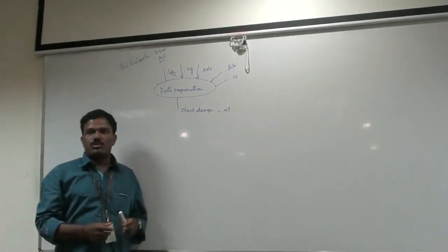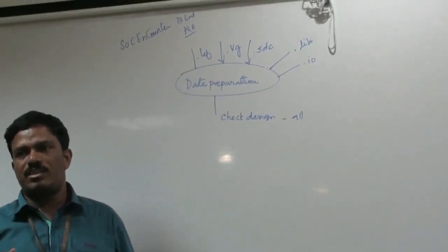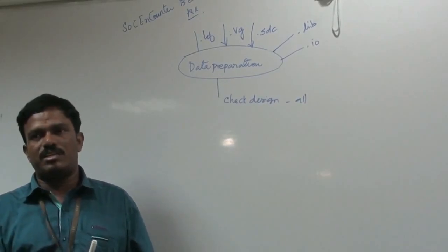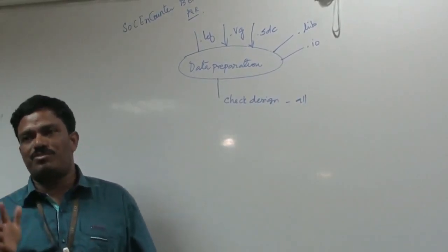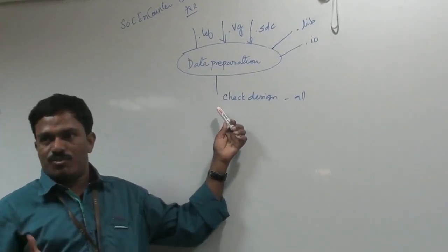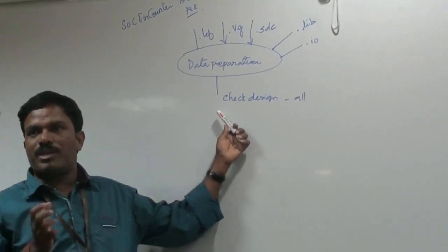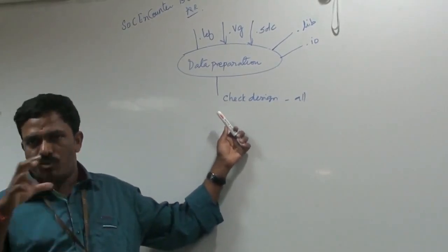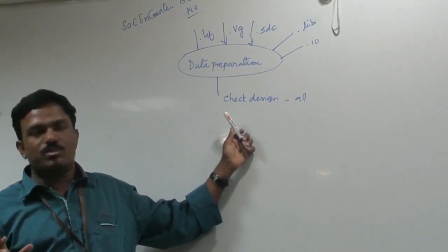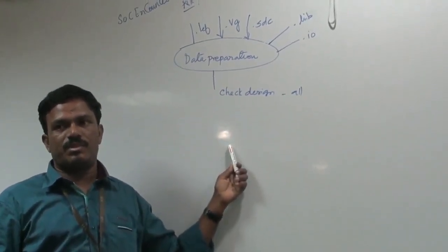So for that, we need to go for check design -R. This is a command that will give you entire information about the design. Before doing the backend, every process is very important in IC design, right? It takes too much time, too much cost. So to avoid mismatches, we are confirming at the initial stage. So whether the RTL fellow gave a proper netlist or not. Is there any floating nets? Is there any multi-fan-out nets? Such kind of verification we are doing in the initial stage.